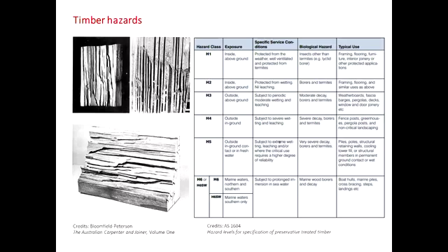And it's not finished, because unfortunately, there are other problems and hazards we need to look at. So mainly, there are two things. The weather is a problem, water, rain. Animals are a problem. In some cases of vandalism, animals can also include humans. But at this stage, we just talk about animals, in particular termites and insects. So termites, what they'll do, they'll just eat your timber products and develop these tunnels.